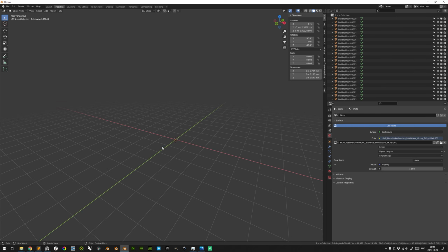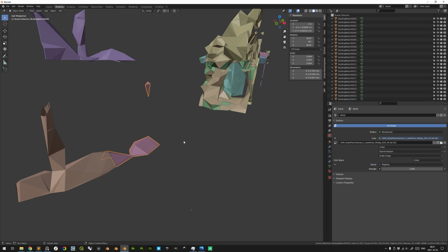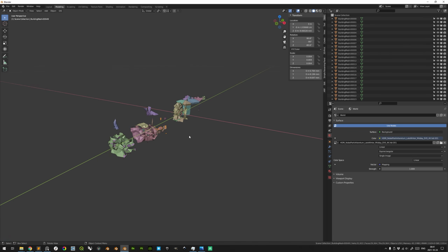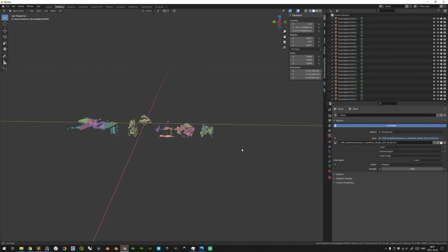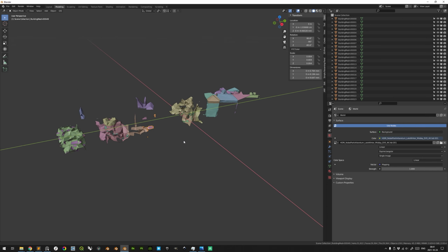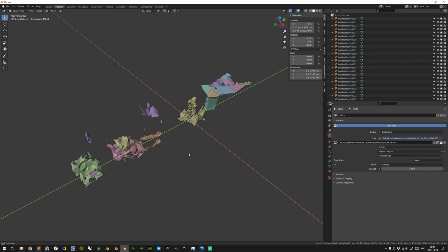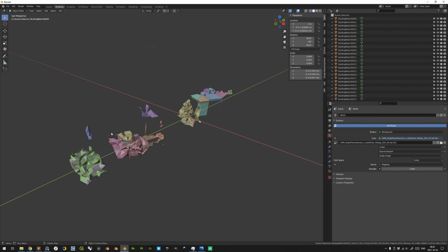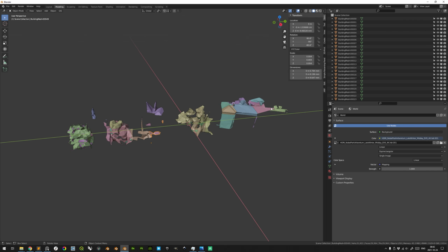And they are positioned around the origin, but as here, they might be very small, so we can simply click the comma or period numpad key, depending on your language locale. For Swedish keyboards, it's a comma, but it might be a period on your numpad. That will immediately zoom in at the selected objects. And we zoom out here a little, and we see here that these 50 first objects were not at all interesting, but it's a lot of foliage and a little part of a building here.